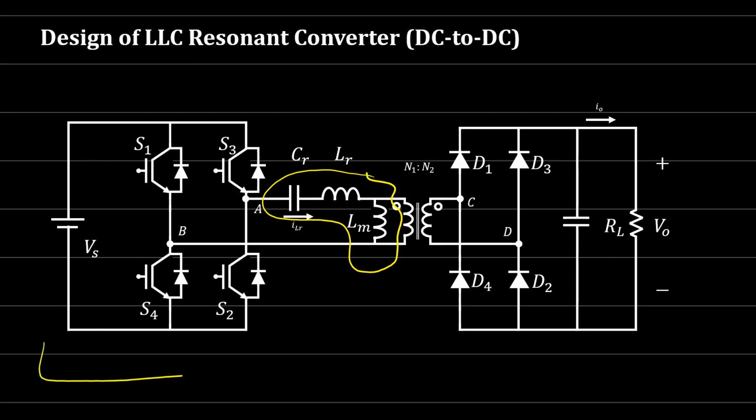Note here that we have a full bridge, because now we understand well the operation of the inverter. So we expect that the output here is a square wave, right? And this is plus minus VDC, not plus minus VDC over 2, because we have a full bridge inverter. On the output, we removed the inductor because we don't have any capacitor. We have a transformer here. We can add a capacitor on the output to make this output a voltage source, no problem.